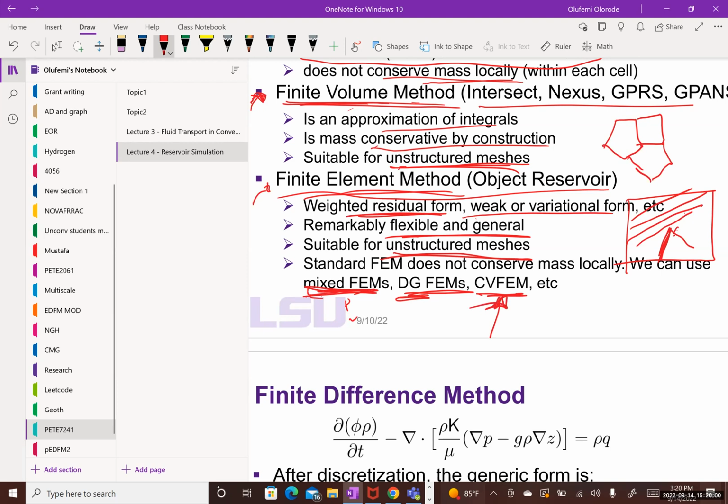So that the centroids of the control volume will be at the nodes. And then when you are doing the geomechanics, the solution for the displacements are the same nodes. So the location of the pressure and the displacements are co-located. That was the advantage of doing that.